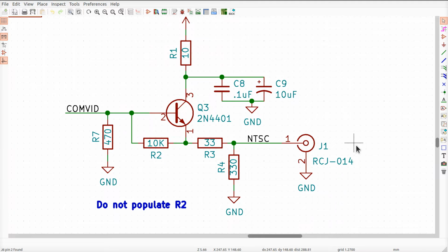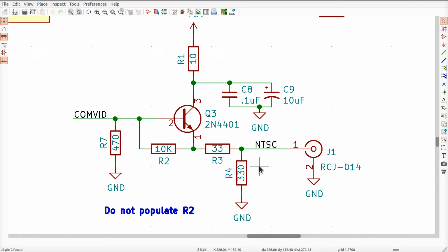Okay? Now, if you don't divide it, it'll probably still work, because most NTSC inputs have an automatic gain control, and it'll attenuate it automatically. But if you do that, you might lose dynamic range, or the color will get all messed up and stuff like that. The color will probably be wrong anyway. I was unable to get a really good consistent color coming out of my chip. And the funny thing is that people in the business say that NTSC stands for never the same color. Because getting the color to come out right with composite video has forever been a problem. All right. So, surprise, our color will probably look wonky.